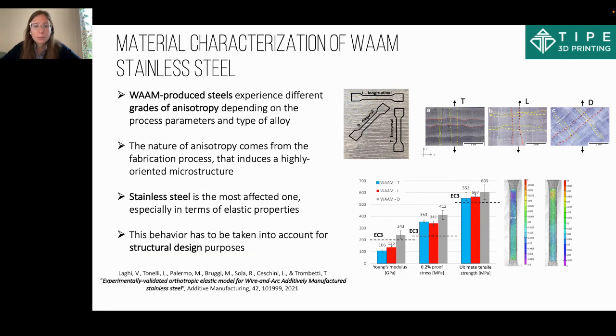The mechanical properties, both in the elastic and post-elastic range, were severely affected by the relative printing direction of the piece. This was in conjunction with the study of the microstructure, because at the micro scale, we found that the crystal orientation was perpendicular to the printing layers.